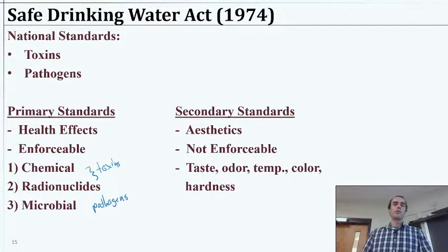There's a lot of things that we wouldn't like, and so there's pretty good reason for the public's consideration why a municipality would want to treat their water to meet these secondary standards. Other things would include the taste, the odor, even temperature. Turns out oxygen dissolves better in colder water, and oxygen tends to impart a nice taste to water. Changes it slightly. So if you ever find yourself drinking lukewarm water or even slightly warm water, you might be kind of grossed out by it.